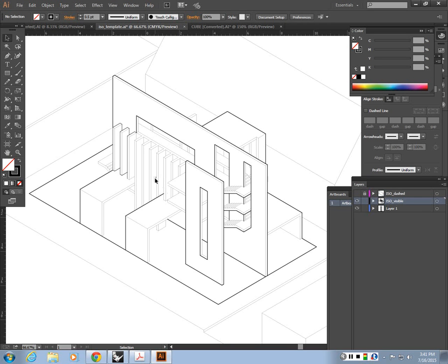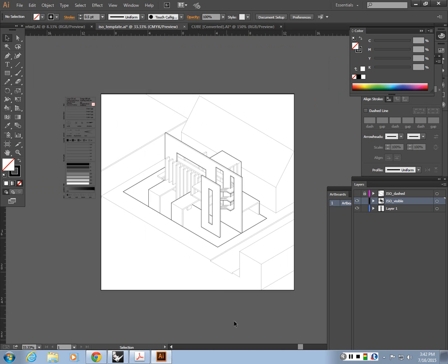And if I were to actually show you, I would probably divide a lot of the edges to apply different line weights to them as well. But we won't have time to do it. So just highlight main elements, main features, just main outlines. Look at the overall geometry and see, okay, maybe this guy could be a thicker line weight, right? And then here, maybe these guys are repeating, so let's make them thinner. In hierarchy, let's bring them 1 level down. So only 3 line weights I want you to use: 2, 1, and 0.5. Alright? And always zoom out from your drawing. Always zoom out and see if you're seeing geometries clearly. That's kind of the logic.